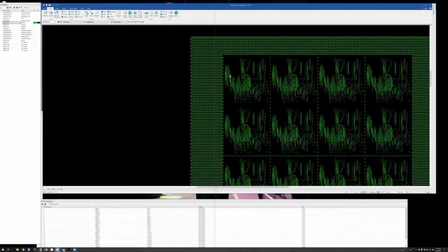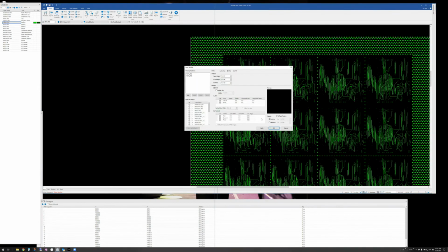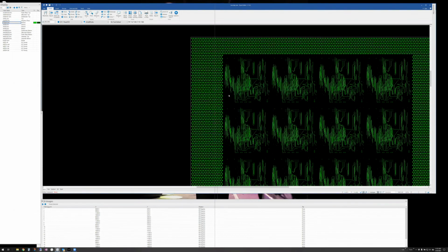The idea is that you create your dot pattern, you get it the way you want it, and then as the last step, you'll go in and, sorry, I need to get the right one here. You'll turn off this allow partials and hit OK. Those go away anywhere where it created those slivers, so it only puts full dots out there instead of creating slivers, so you don't have problems.